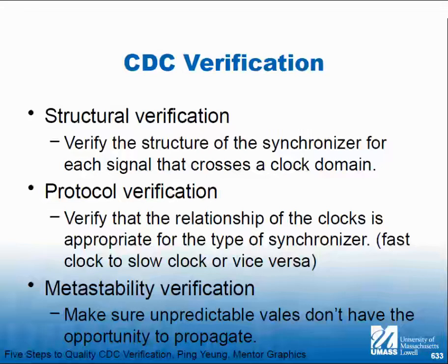When you had the output of the flip-flop, there was a gate on the output that would decide majority, best 2 out of 3. So almost all the time, the 3 values would be all 1s or all 0s, but every once in a while it'd be 1 1 0 or 1 0 1 or something. And the logic would do 2 things. It would report the right state, and it would rewrite the flip-flop so whatever one was wrong was righted.